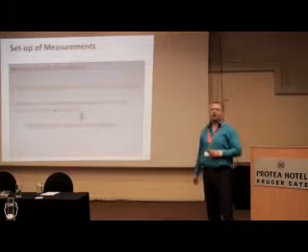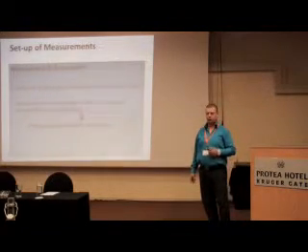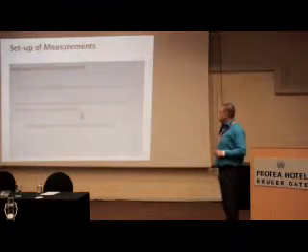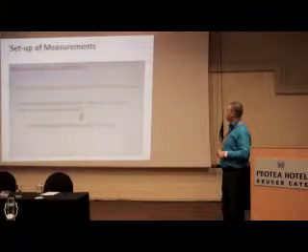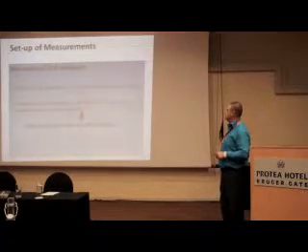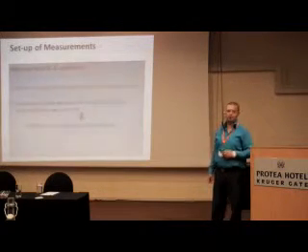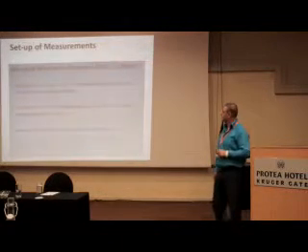It's a device that allows the 50 Hertz, 220 volts to pass through and stops all the communication signals. Here you use a transformer to start the LISN because the LISN causes an earth leakage current to flow, which trips the supply. Floating the LISN itself rectifies this fault condition.